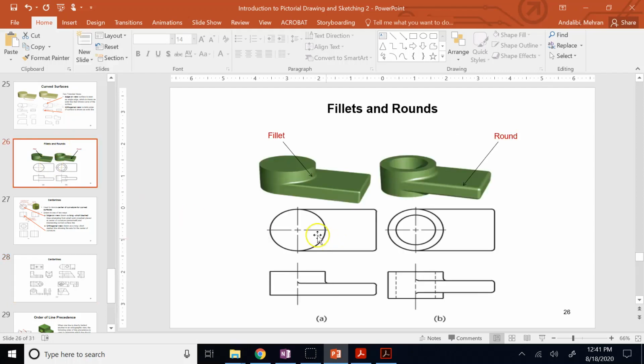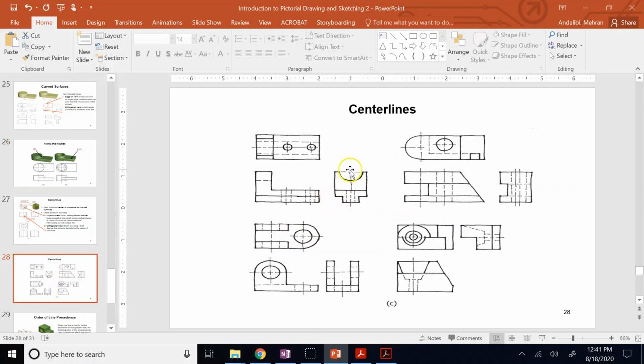And so instead of using two full dash-dotted lines forming a cross, you show one dash-dotted line completely, and the other one you just show half of it. As you can see, this one is half. It does not extend beyond the center upward. This one does. It goes left and right. This one does not. So you show basically half of everything, or 3/4 of everything of the axis of symmetry, right?